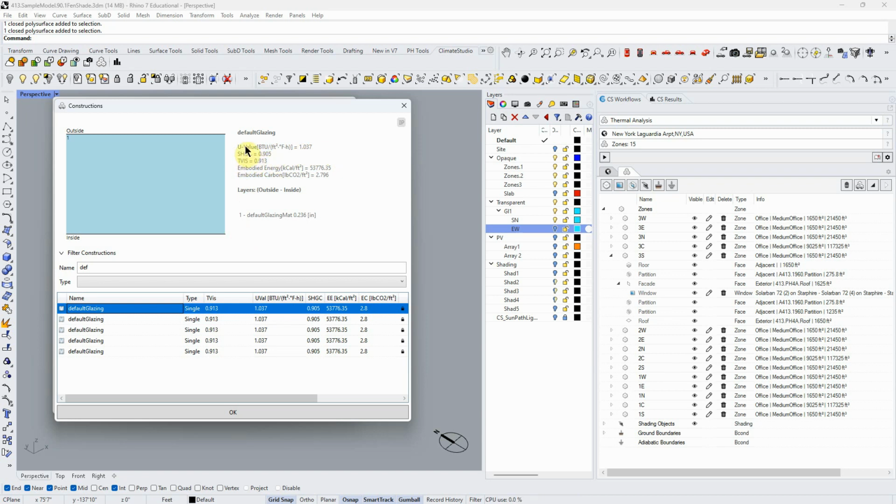Solar heat gain is one of the variables. Solar heat gain coefficient is the percentage of solar heat that's going through the glass. So this is letting in 90% of the heat that's hitting it, which is great if you're trying to collect heat, bad if you don't. The visibility is the same. It's a ratio, so this is letting in 90% of the visible light. In the electromagnetic spectrum, different wavelengths are for heat and for visible light, so those are different numbers. In high performance glazing, I'll show you some in a second, we can do amazing things by changing these numbers. You have to be careful.